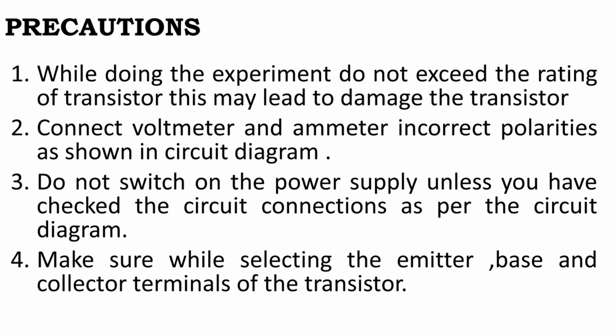Precautions. While doing the experiment, do not exceed the rating of the transistor. This may lead to damage to the transistor. Connect the voltmeter and ammeter in correct polarities as shown in the circuit diagram. Do not switch on the power supply unless you have checked the circuit connections as per the circuit diagram. Make sure when selecting the emitter, base and collector of the transistor.